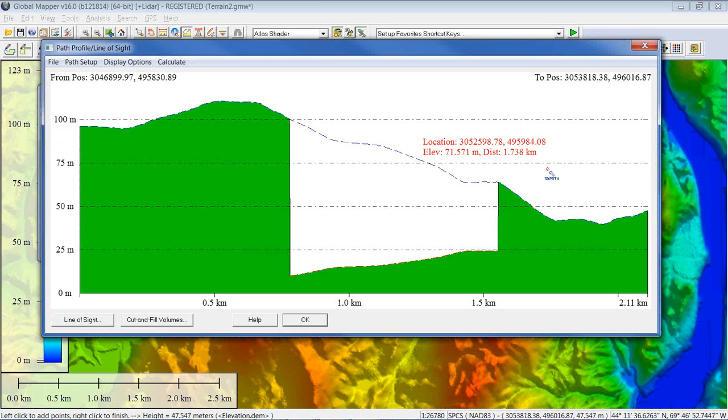You'll notice now it's able to generate a profile of both. The dominant layer, the one that physically is sitting on top in my map, is the one that you'll see shaded. This green outline represents the combination of the original surface and that subsurface layer. Perhaps this is a geological discontinuity or a bedding plane or something of that type. But you'll see that profile now representing that horizon as opposed to the original. You will, however, see the original horizon in a dashed form. So this shows you that you can create a profile across multiple terrain layers.